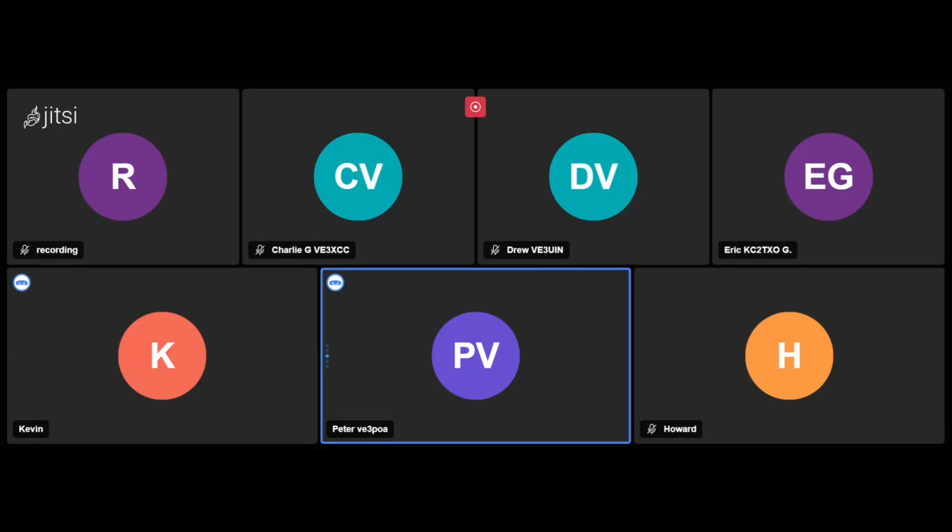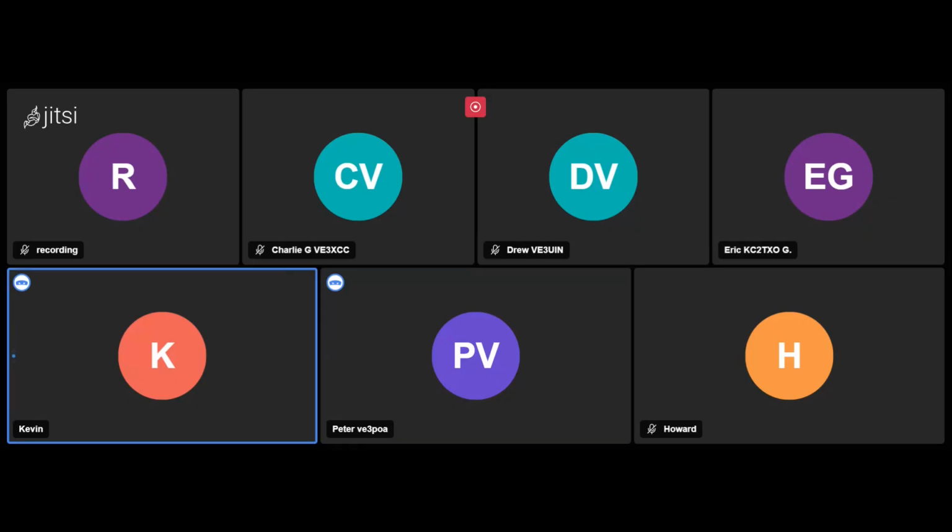I think actually this library is called Fix something. Fix FFT. Yes, that's the library. That's a fixed point one. It's speed over precision, right? So that's like we was just saying, you lose precision if you're going to go to integer math. But there's another one that goes up to 256 bins.